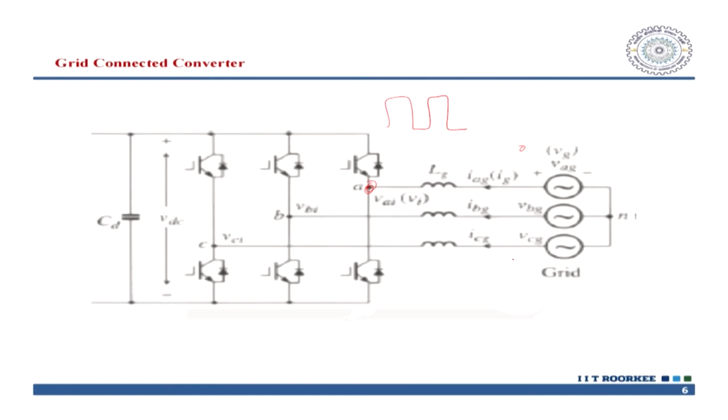And it may act as an active rectifier, sometimes, because you may have a bulk of batteries to be charged. So, you require to charge in a sinusoidal fashion. And the reverse can also be true, because you may have a peak management control, especially in the evening. So, you want to feed the power from the storage element, or you may have a solar, then power will flow back from the DC side to the AC side.